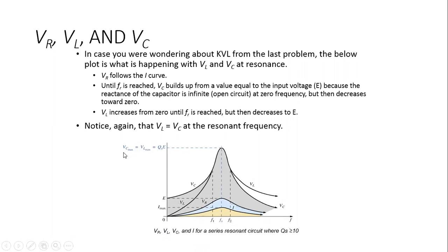So here, if you are getting the maximum voltage across the capacitor, definitely the voltage drop across the inductor will be the maximum. How can you get this? With the help of the voltage drop across each along with the quality factor. So here, as per the resonance circuitry, VL is equal to VC because XL is equal to XC. So definitely the voltage drop across the inductor and the capacitor will be equal.